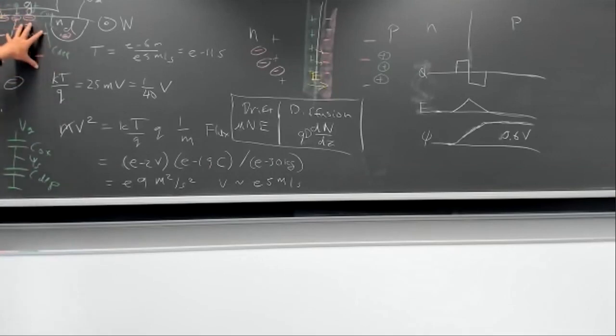there's no electrons here, right? So the way you get the electrons quickly is from the source. Yes, so you need that. If you're going to make a MOS capacitor, you need that source there. Otherwise it won't work very well, or it'll be very, very slow.